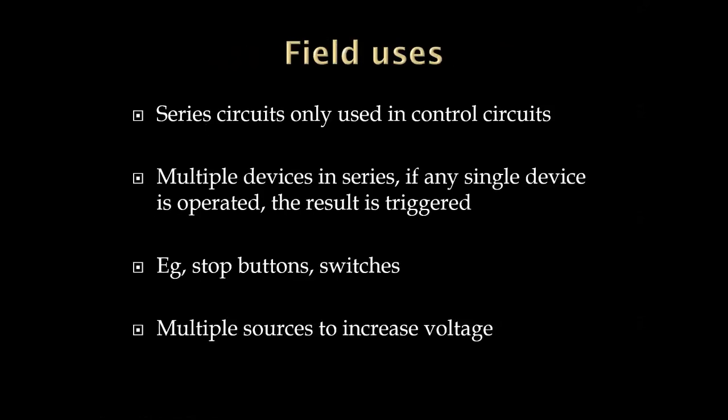Okay, so we're not using this for power. Where we are going to use this is for control circuits. Multiple devices in series: if any single device is operated, it's going to trigger my result. What we're talking about is like stop buttons or switches. If I have a stop button and I trigger that button, I want it to stop whatever it was powering. That's why we call it a stop button.